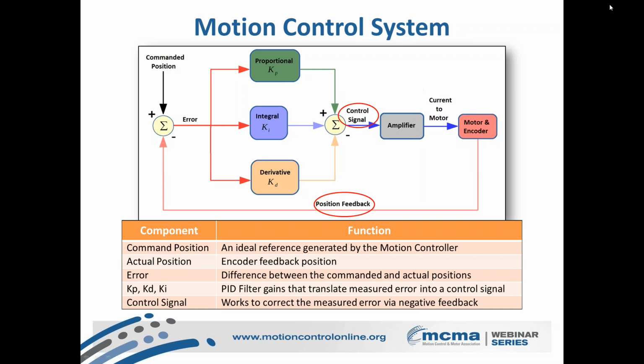The other major downside to these protocols is latency. In order for that information to get from the controller to whatever node it needs to go to, the controller needs to produce the data, wrap it up in an appropriate packet that matches the protocol, then send it down the line, and then the node on the other side needs to take that data, unwrap it, and route it appropriately. And this is non-negligible time for the purposes of motion control.